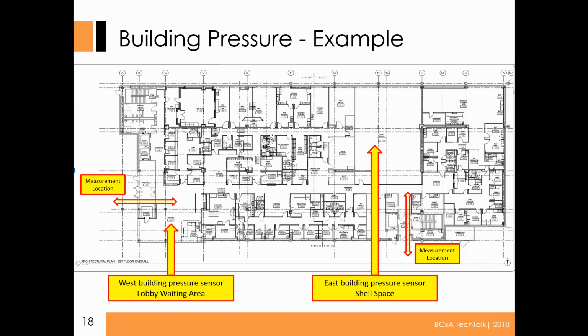Where is this building pressurization measured? Really important you pay attention to this. So on our west unit, that would be this half of the building, the west side of the building, we have our main lobby right here. We have a revolving door, a vestibule, a double door. So a great design to mitigate stack effect, by the way. That's a good design. Vestibules are super helpful.